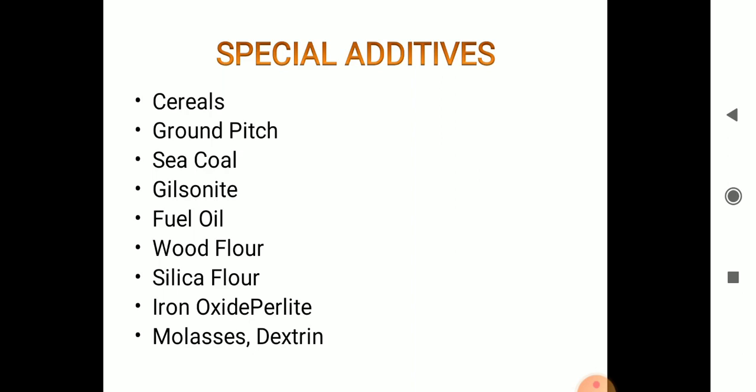Next is silica flour, finer than 200 mesh. Silica flour up to 35 percent increases hot strength. Next is iron oxide, 0.25 to 1 percent, to obtain added hot strength. Then perlite, an aluminium silicate mineral, 0.5 to 1 percent, gives better thermal stability for riser insulation.